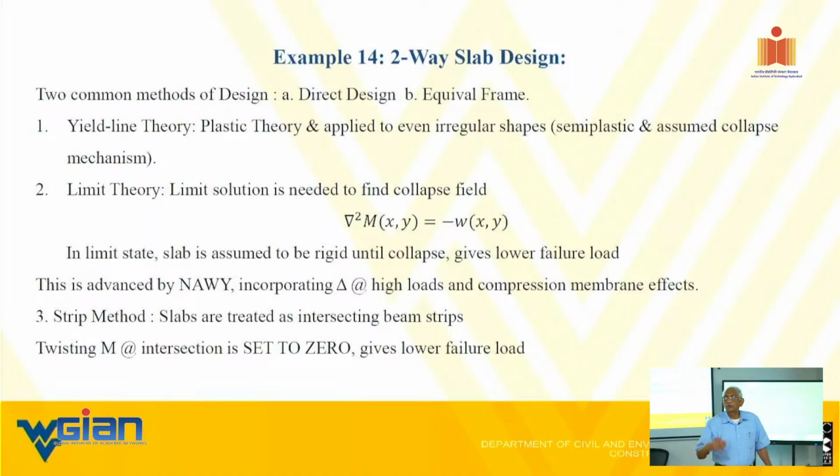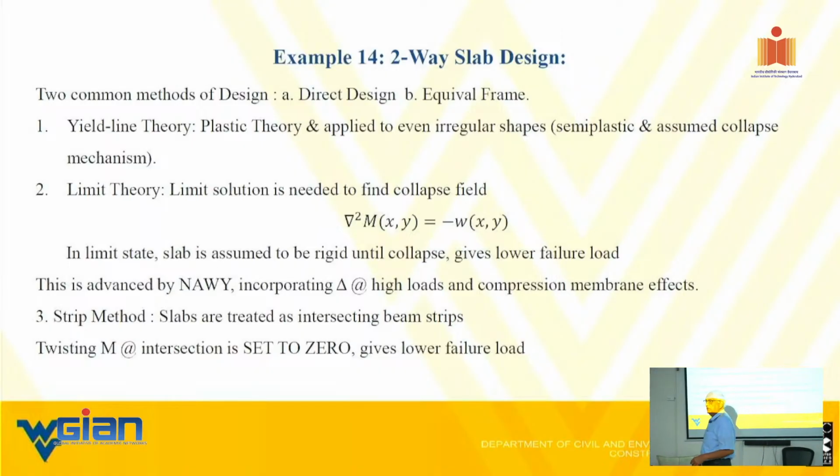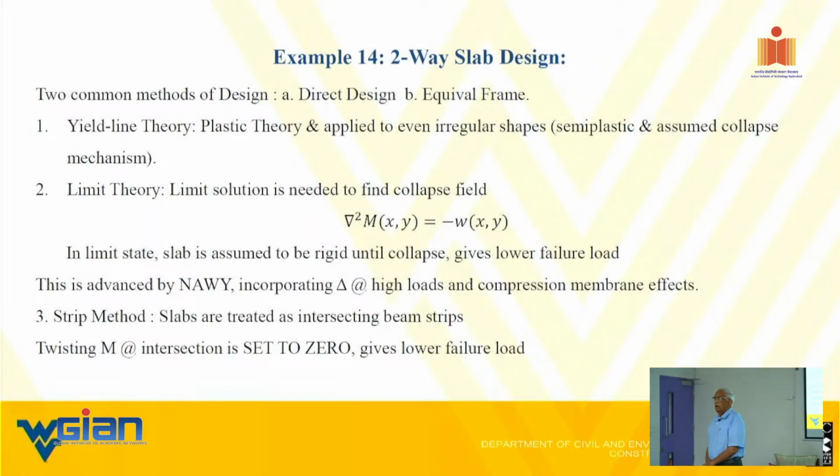So how do you know it's going to maintain 60 KSI or not after 10 years or 20 years under different kind of environment? If this is guaranteed, you are absolutely right. At this point, I don't know whether I am going to be able to guarantee this number after 10 years or whatever. That is the reason we need to. It's over-reinforced. It is driven by the concrete properties, no doubt. But at the same time, I need to make sure my minimum properties of FRP are maintained.